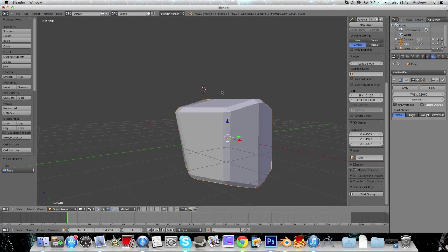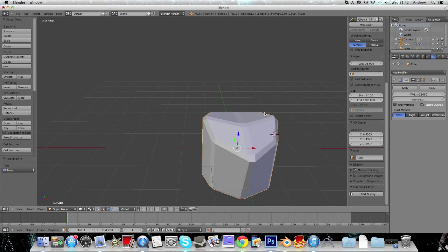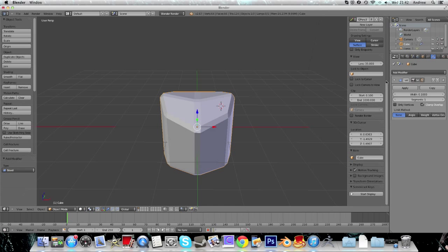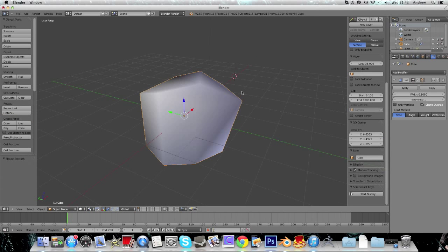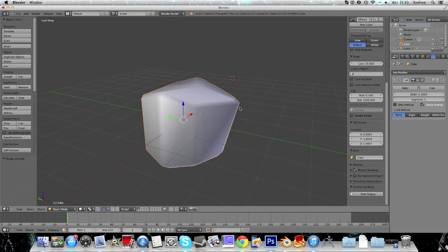You'll see this effect on certain shapes, and it does make some shapes like cubes look nicer. If you're going to have them in your scene, you might want to bevel the edges to make them look good. That's just the modifier, so it does it all automatically. What it also helps with is smooth shading. You can see how smooth shading looks here, but if we've got sharp edges, which now it does, the smooth shading doesn't look very good. If we add smooth shading with the bevel modifier, then you can see that looks a lot better.